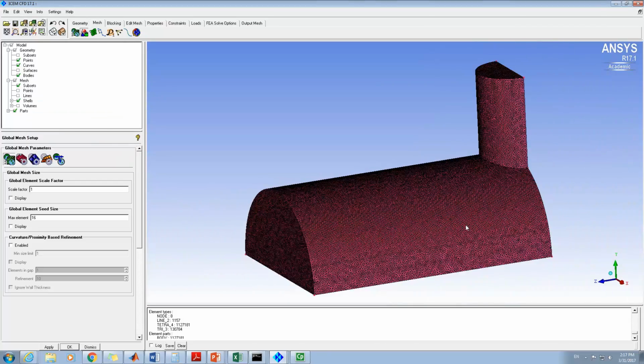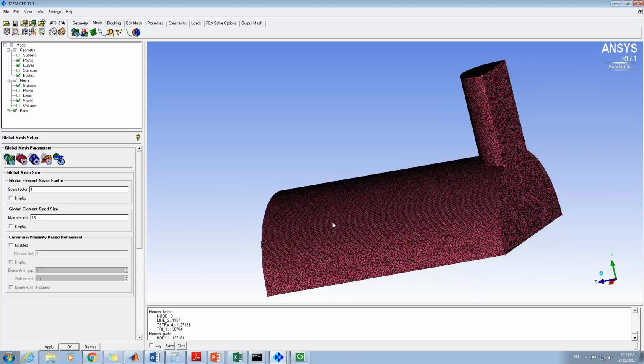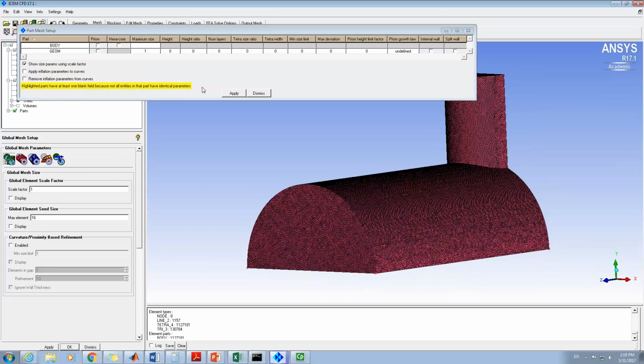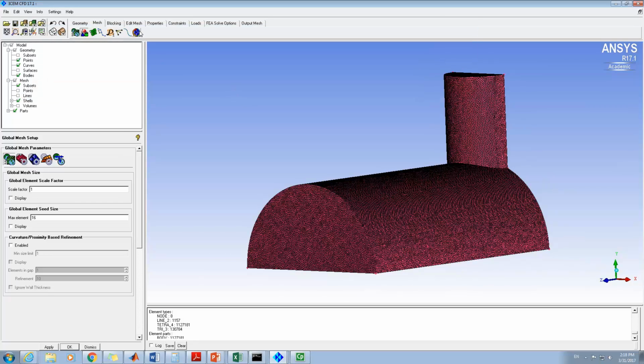Anyways, this is how we create an unstructured mesh. You can see the procedure is really simple, right? You first create a material point inside of the geometry, then you set up the mesh size, then you just click this Compute Mesh button, and the unstructured mesh will be created for you. So you probably wonder why we then want to use structured mesh, because creating an unstructured mesh is so simple.